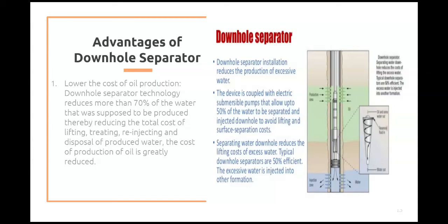Engineers can carry out production without worrying about water that must be treated. Hence, they will be reusing the water to re-inject in the formation. By doing so, the cost of production of oil is greatly reduced. Based on the image on the side, downhole separator installation reduces the production of excessive water.